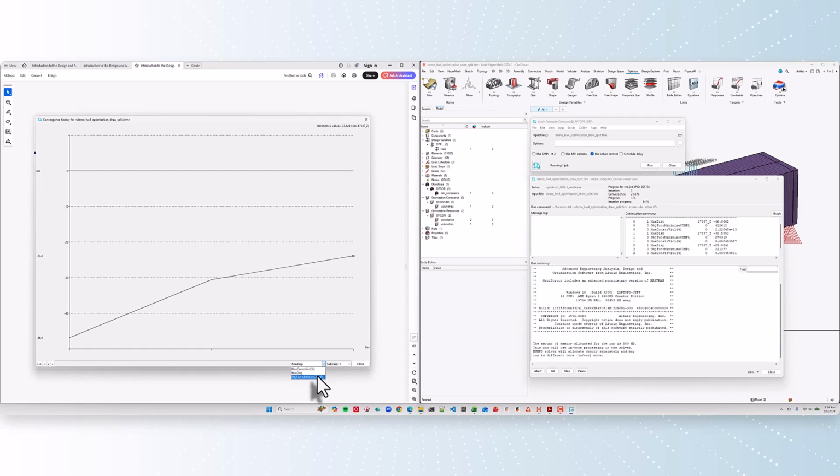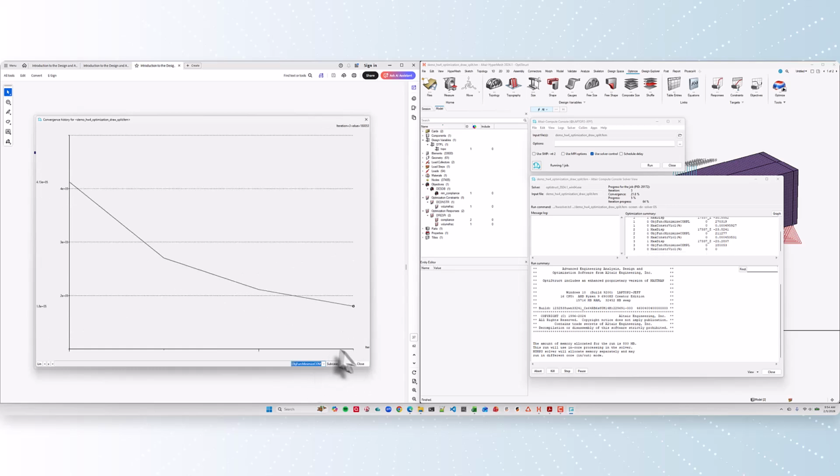But what is it I want to plot? Well, I want to plot compliance because the objective was minimize compliance. So I should watch this curve continue to go down until it hits a minimum. This is the curve that I watch to see if the optimization is progressing well. So let me let it finish a couple of iterations, and then I'll pause the video, because I think it takes about 10, maybe 15 minutes to solve completely. So I'll pause to save video time, and then I'll come back on when it's finished, and we'll pick up again.